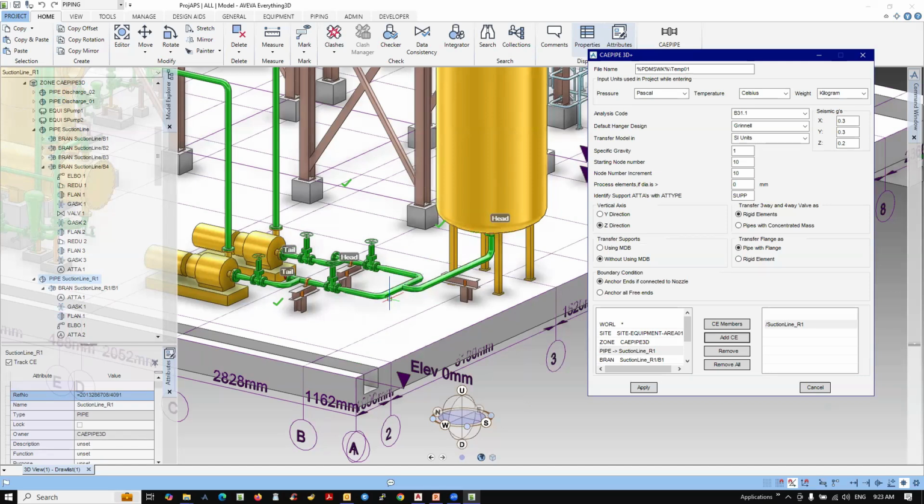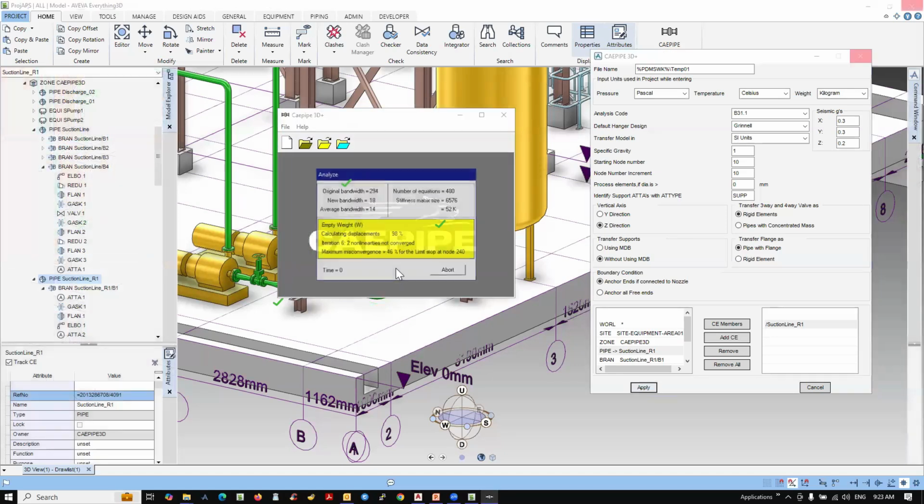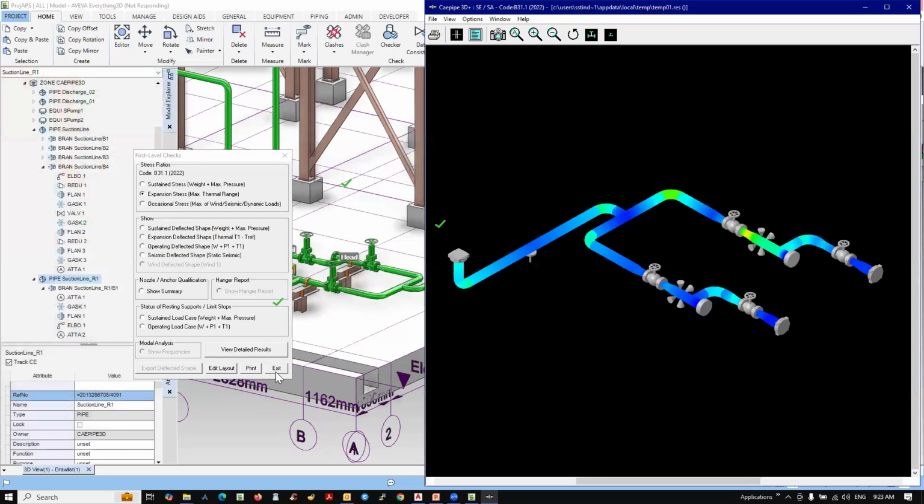And instead of that, now he has added a T-joint here at the middle of the pipe, and he has added just a bend. By doing this, he has made this entire thing more symmetrical. Now in the process, again, when you do the check stress, you can see that it gives you output so quickly.